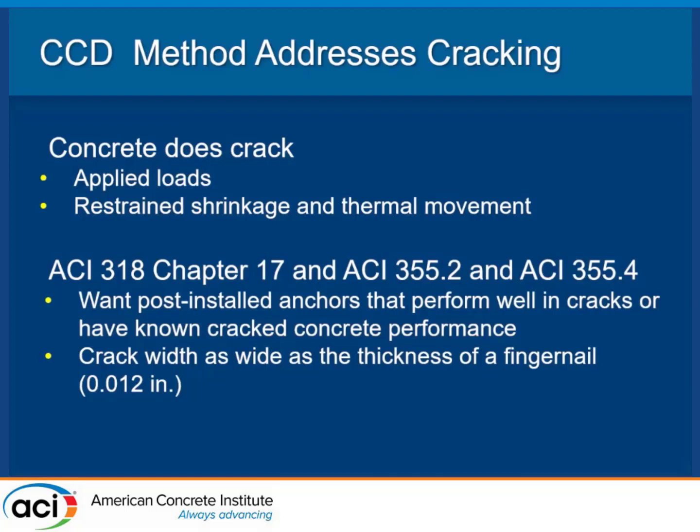Okay, so concrete does crack, right? So we want to address that. We do require in 355.2 and 355.4 that we make them test with a crack, and that crack width is 0.012 inches, basically the thickness of your fingernail. So if you're out there walking along, you're seeing cracking, and you put your fingernail in there, and it's much larger than your fingernail, you probably aren't meeting the capacity that you designed for. Okay, but they are good up to that thickness of crack.